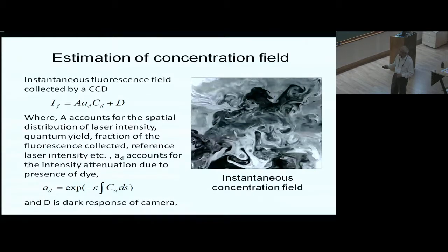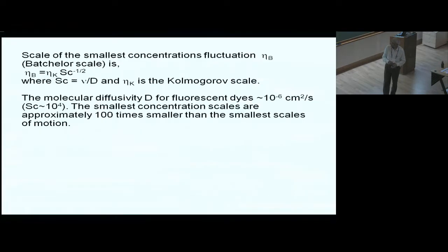So the Prandtl number is very large here. The viscous layers will be much thicker compared to the density gradients which you get. That will be the Batchelor scale. The Schmidt number for the dye itself is 10 power 4, and for the salt it's around 600.